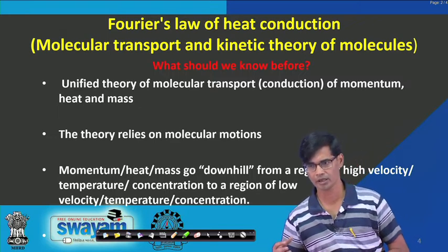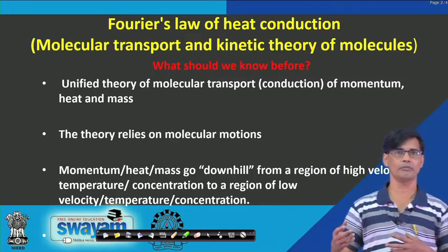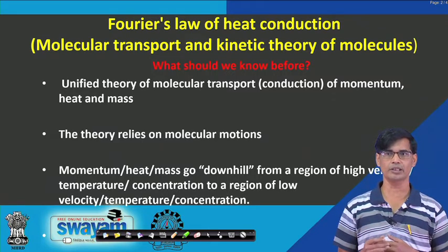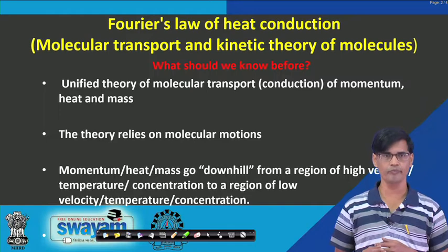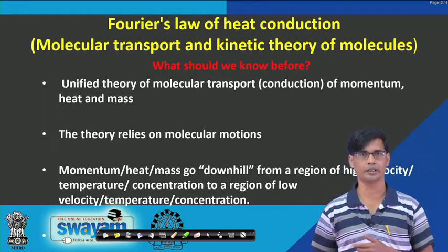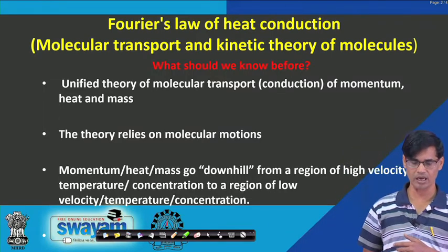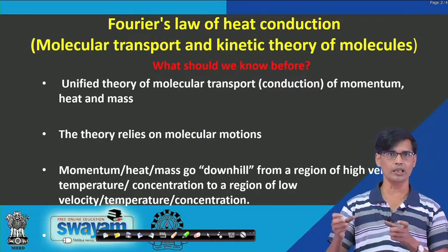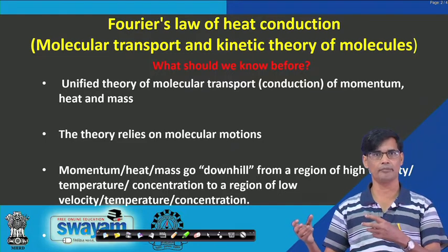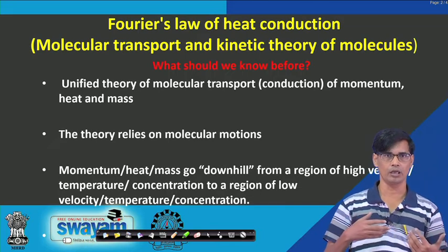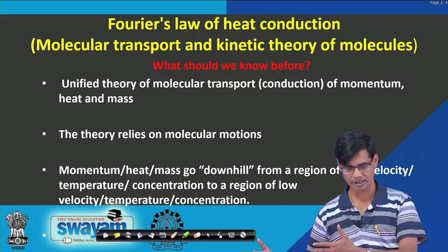Molecular motion means that even if there is no bulk flow, no velocity of the molecules, the molecules themselves move on the basis of the kinetic theory of molecules, and there are three components. One is the rotational motion, another is the translational motion, and the last one is vibrational. So, three molecular motions are there. Even if there is no bulk flow, that molecular motion is responsible for transferring momentum, heat and mass from higher region to lower region.